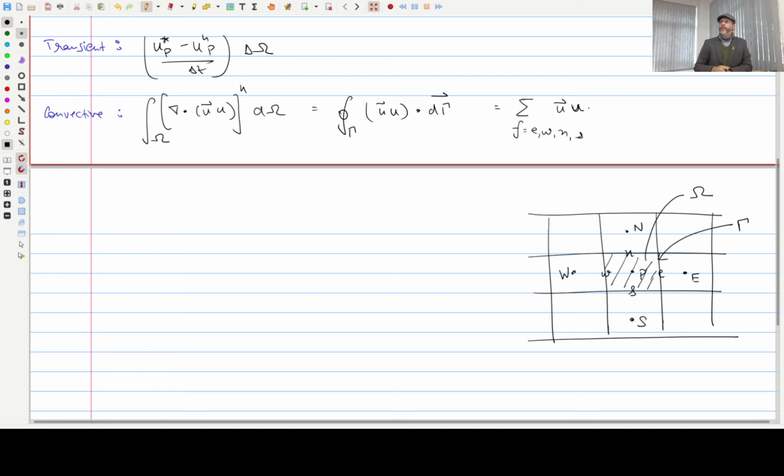The u vector is coming from the velocity, and the small u is coming from the fact that you're solving the u equation. So let's remember what we discussed in the 1D wave equation. There, we had a u vector times phi. Phi was a scalar being transported, and u was the velocity vector transporting the scalar. But this time, when you solve the momentum equation, it's the velocity that is transporting the momentum, or velocity terms u and v separately.